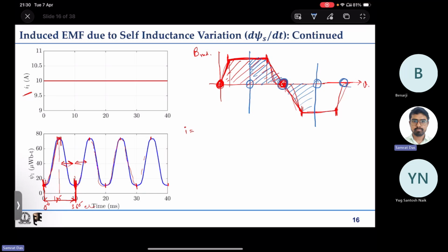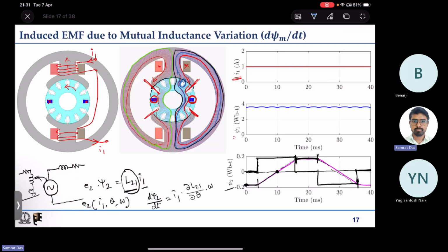Now you have to take the integration from pi to 2 pi, so it is negative. So whatever sign of flux linkage you got when the coil was at 0 degree and 180 degree, you get the opposite when the coil is at 180 degree and 0, which means it has rotated by 180 degree. This is how you get it. Does it answer your question? Yes, sir. Okay.